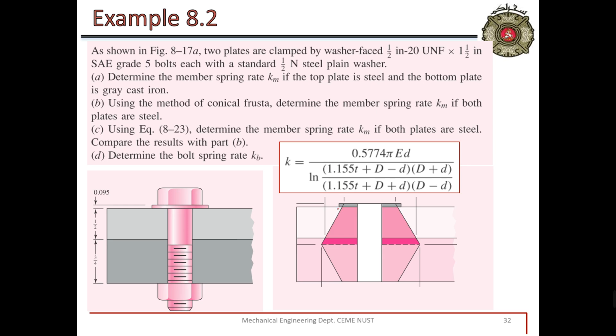Then we solved this example. In this example, I just wanted to explain the function of the frustum. Here, they have given in the question the thickness of material 1 and also the thickness of material 2, ½ inch, and this is 0.5 and this is 0.75. So if we move from this point to this point, the total length is grip, and grip by 2 in this.